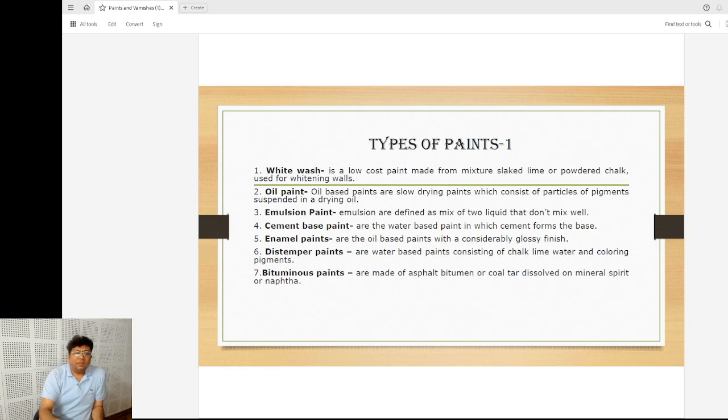For example, the most economical and the cheapest paint is whitewash, a cement based whitewash which is done directly on a cemented wall. It is mostly done in public places, where you have to paint the surface every 6 months or a year. It is not very durable, but after whitewashing a wall it gives a freshness. So when you need the walls to be fresh after every 6 months, we should whitewash the surface.